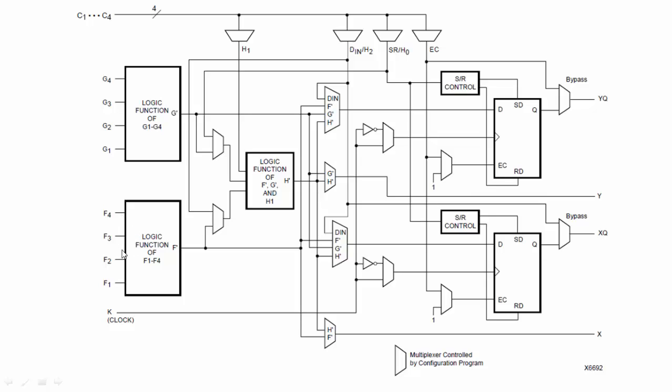Also we have said that these are independent. Why? Because from the external circuitry out of the FPGA kit, you can have any input and route it through your input output block, and that can appear at the input of the function generator. So this function generator is able to perform any function.